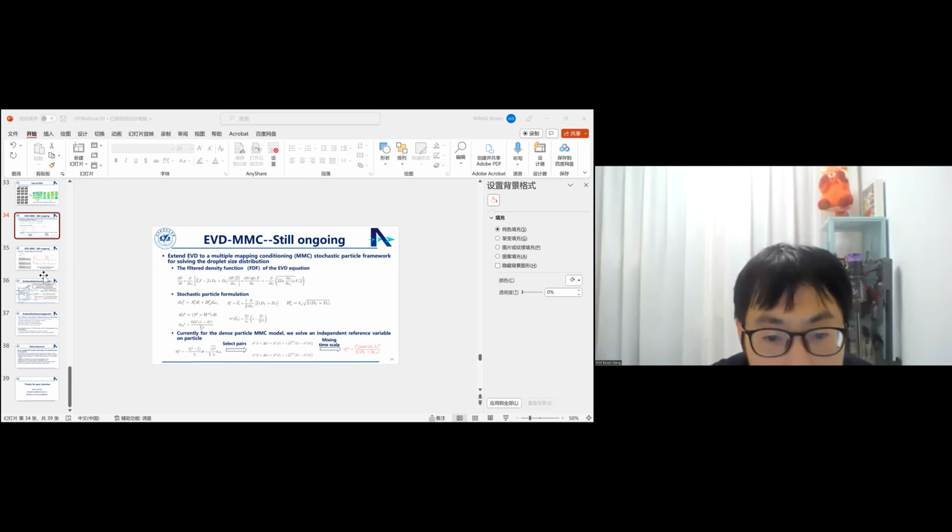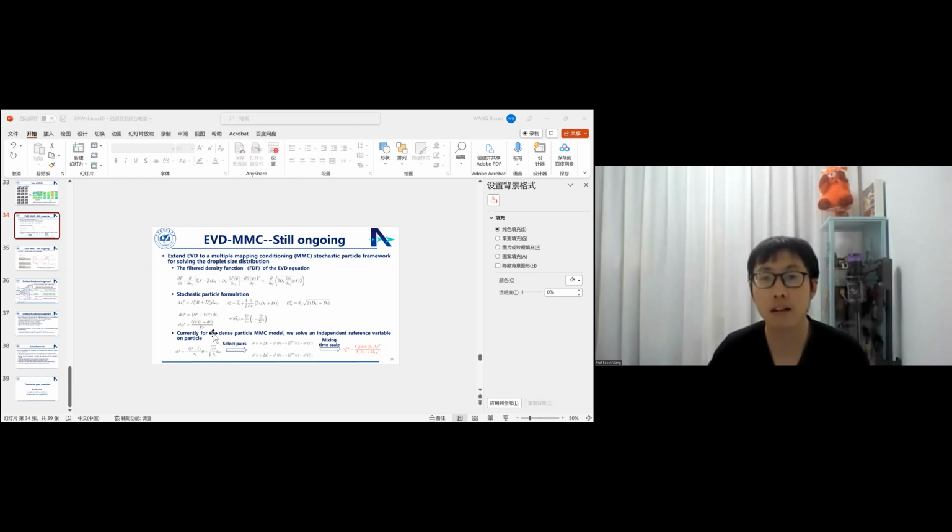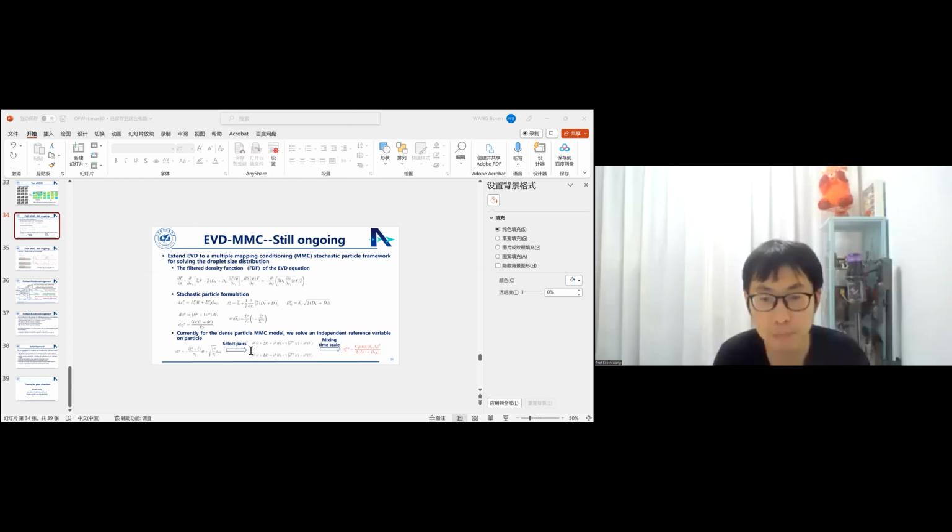We define it relative to the boundary layer thickness near the interface, and this interface boundary layer thickness can be determined by the Reynolds number of the jet and of the gas flow. Then we need to make sure the grid cells resolve well the physical volume scale as well as the boundary layer thickness. And then we refine until we get grid convergence.